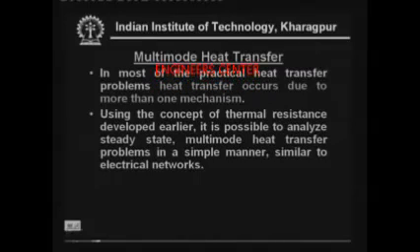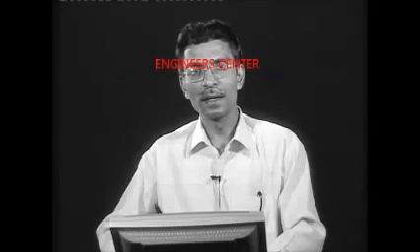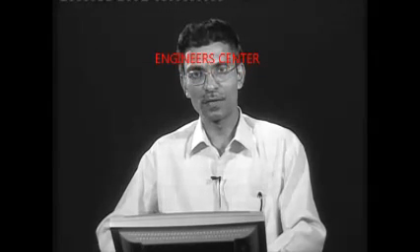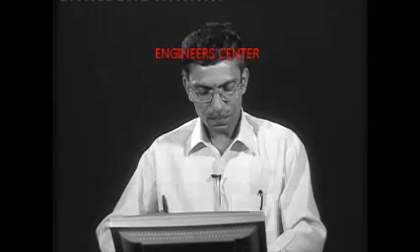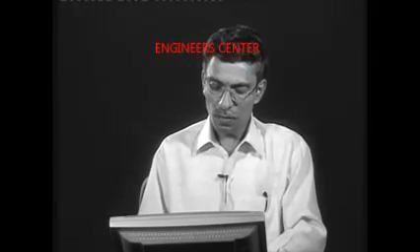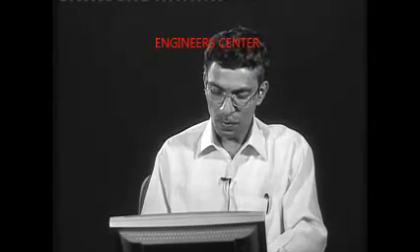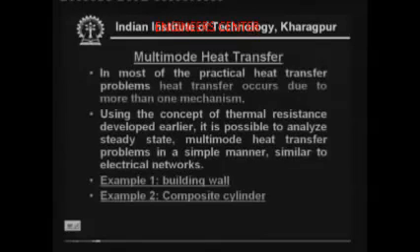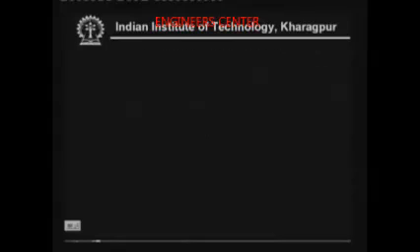If you have unsteady state problems, you cannot directly apply the concept of thermal resistance and networks. Now, let me give an example of a building wall.